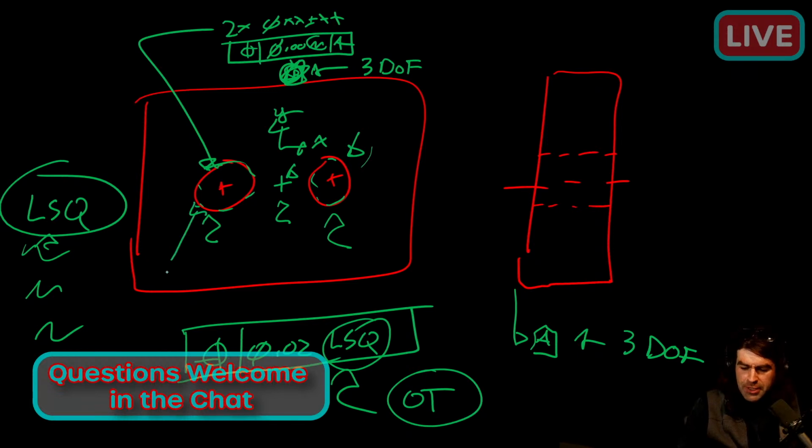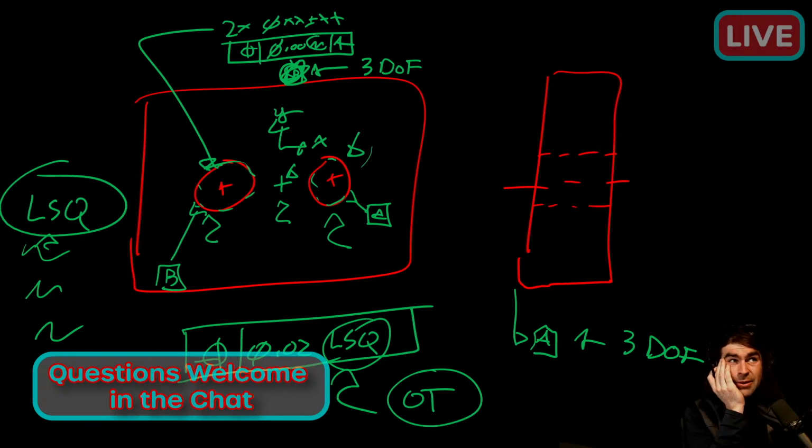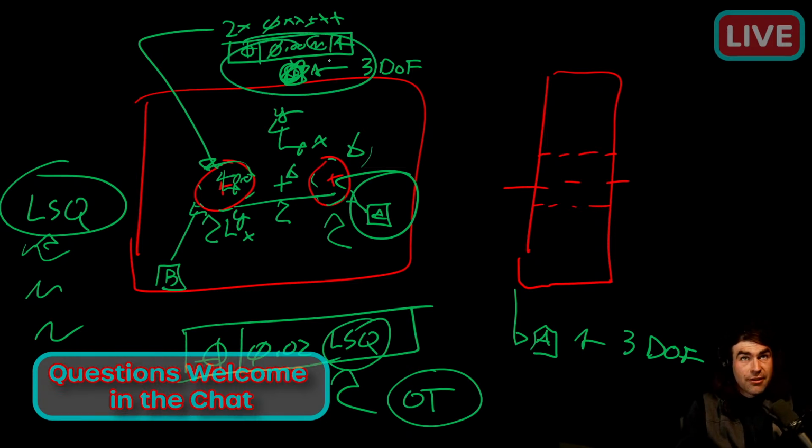You see this with PCBs a lot. You'll see datum B, and then over here will be datum C. And that, yeah, you would need to set up 2 different features. Oh man, now I gotta really think. Yeah, so this would be your X and your Y origin right here, right? You're basically at 0, 0. And then you're measuring this hole to there. And here C is just setting rotation. It's a little weird, right? I would recommend doing it the first way, unless you have a really good reason not to.